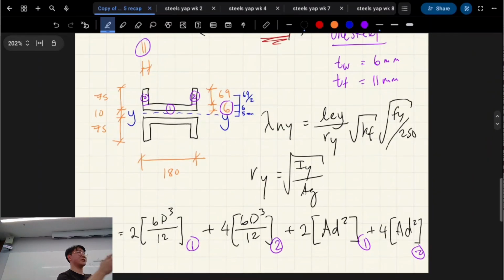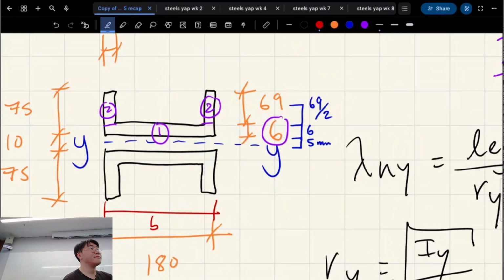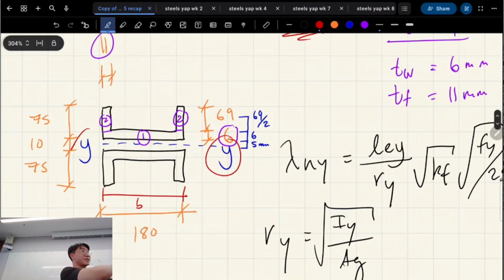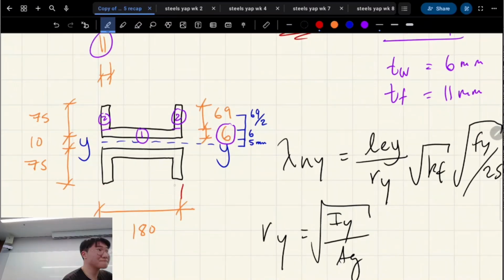So it's relative to your perspective, and as long as you have the correct dimension in terms of the solid mechanics, it doesn't matter what you call B and what you call D. I could have called this B, but I've just decided to call this B. I've rotated it 90 degrees, so the y axis cuts horizontally. You're thinking of it relative to when y cuts vertically. So B is labeled the way that I normally think of it, as if I'm looking at it like this, but y has flipped. That's all that's changed.